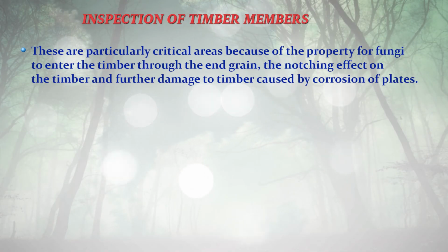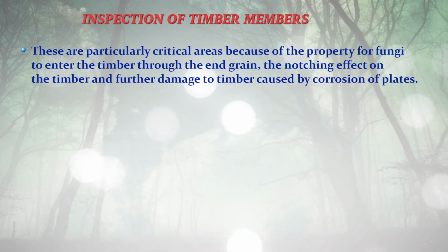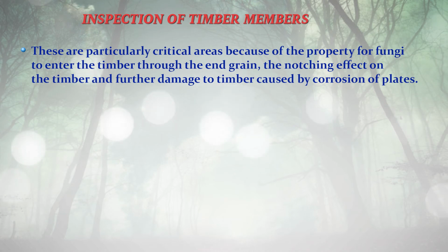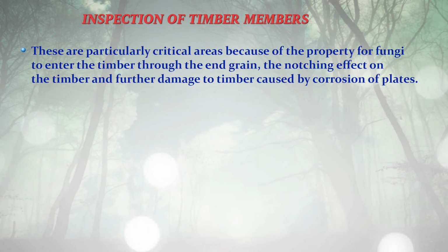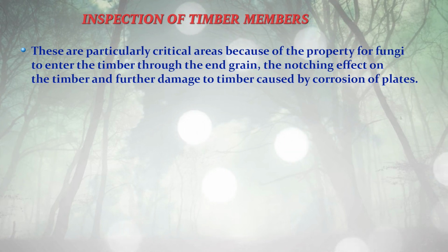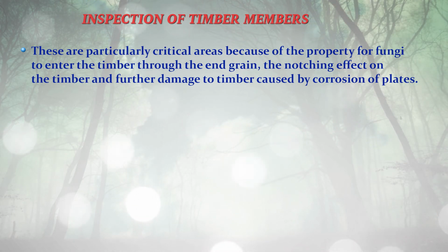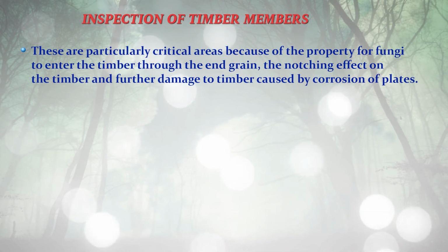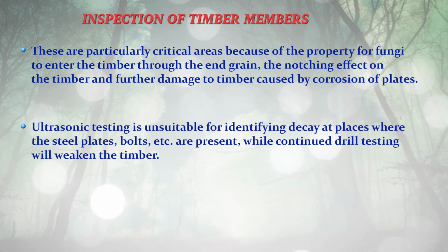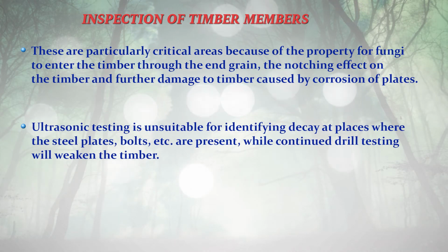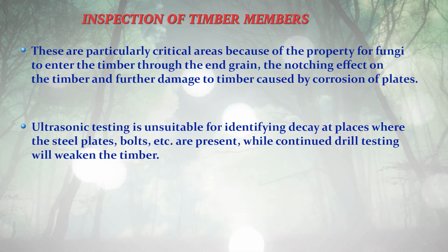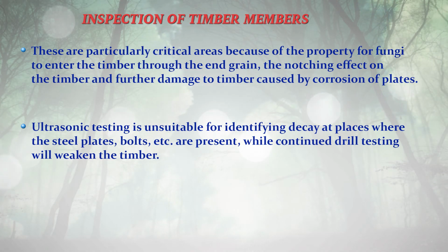These are particularly critical areas because of the property of fungi to enter the timber through the end grains, the notching effect on the timber, and further damage to timber caused by corrosion of plates. Ultrasonic testing is unsuitable for identifying decay at places where the steel plates, bolts, etc. are present, while continued drill testing will weaken the timber.